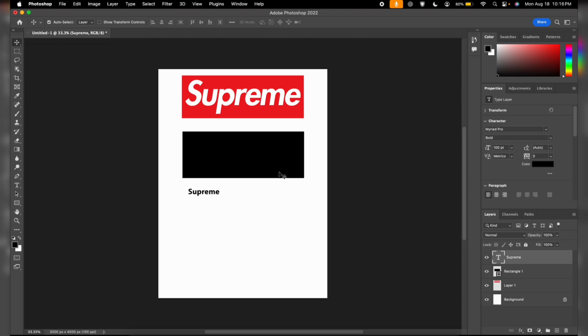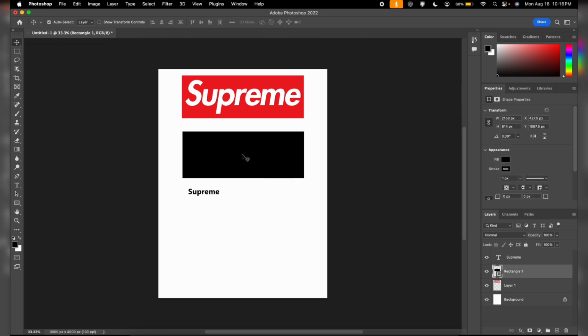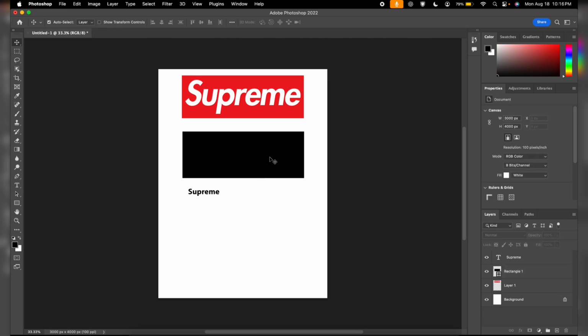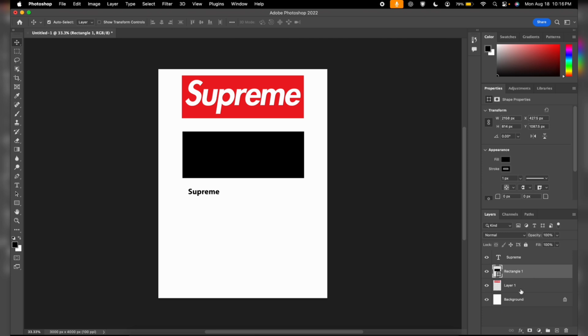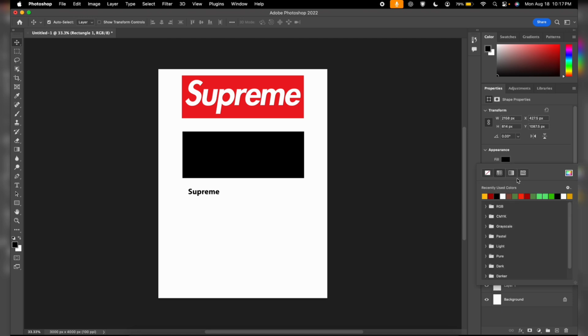After that, to start our adjustment, I want this rectangle in the red color. So you click on the rectangle. Whatever layer you want to adjust, you have to make sure you are clicking on it. To confirm that you've clicked on it, you will see it here on the layers panel. You can see that right now we have the rectangle highlighted. So you come here to change the color. You come to this view. We'll talk more about this soon. So you come here, you change your color.